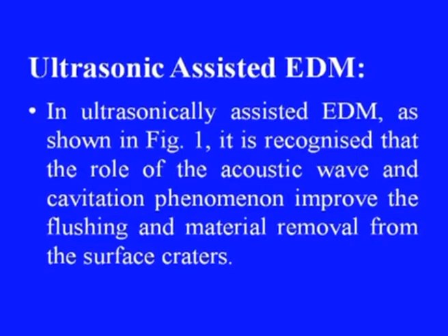This is another hybrid process of EDM. In this process, as we can see in the figure later, it is recognized that the role of acoustic wave and a cavitation phenomenon improve the flushing and material removal from the surface craters. These process conditions are significant for micro drilling and production of slots and grooves.